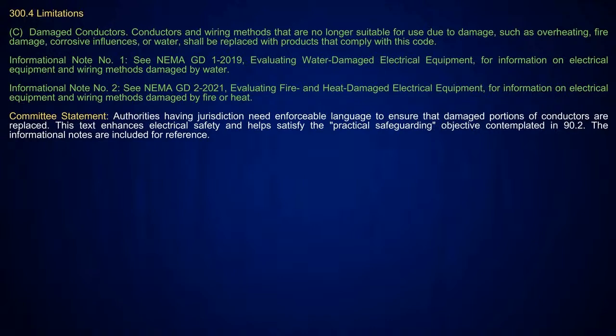Sure. Now, this one is where they have now placed enforceable language. And this is to help take care of where you could have damaged conductors. They're basically telling you here that when you have conductors and wiring methods that are no longer suitable for use due to damage, and this could be items such as overheating, fire damage, corrosive influence, or water, they are required to be replaced with products that comply with the NEC.